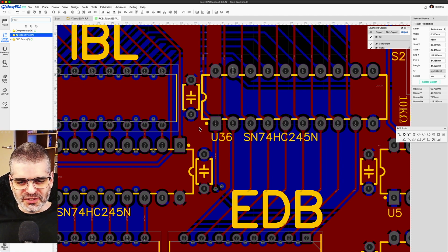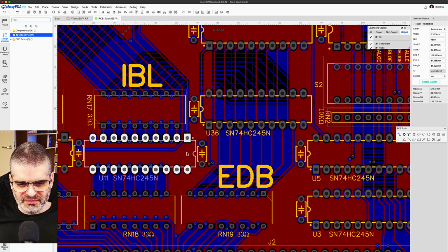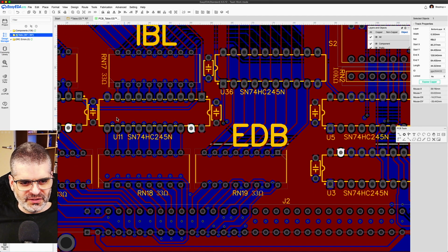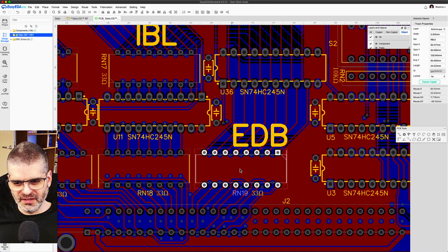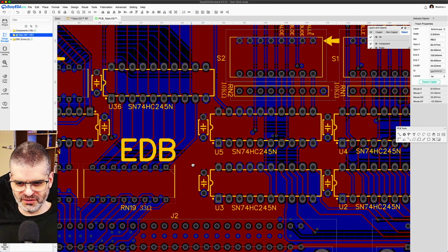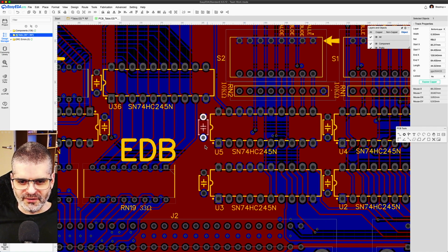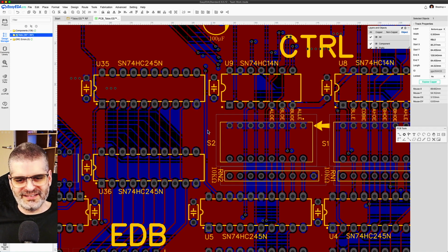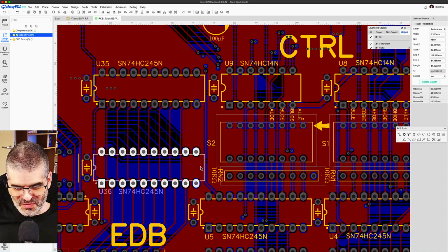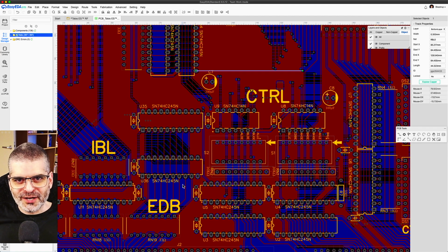In this case, it's not really a problem, because if we follow this further, we will see that the power can also come from here, here, here. You see, it goes into this area here. It's a dead end on this side, but going up, look, there's a lot of space here. There is more space here, here, here, here, here. Through this side, this way, that way, that way. It goes up, and then there's a lot of power. So it's okay, but it was not when I did the copper fill at first.